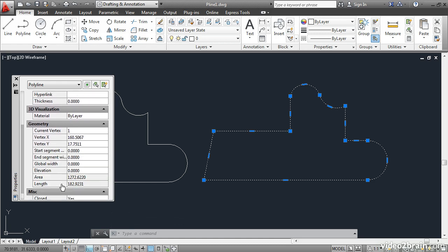In summary, you have created complex polylines with both straight and curved segments, have discovered area and perimeter values associated with polylines, and finally have exploded and rejoined segments back into polylines.